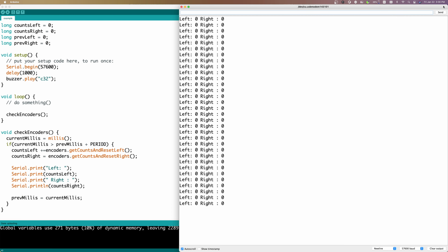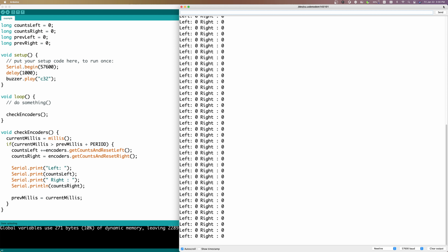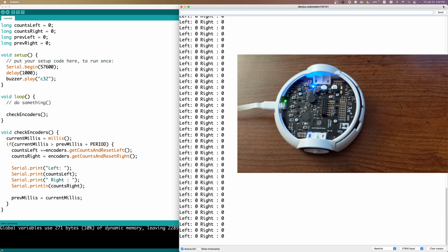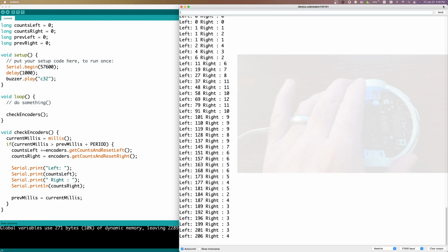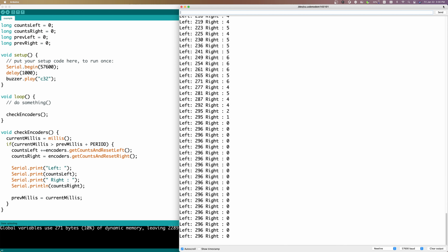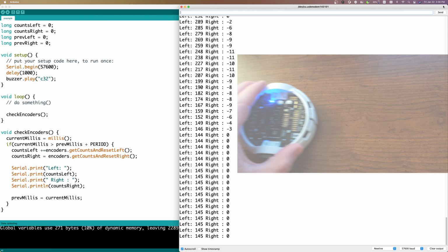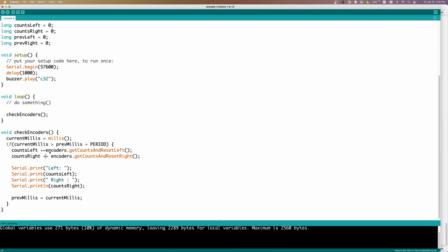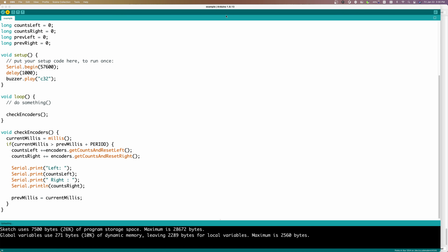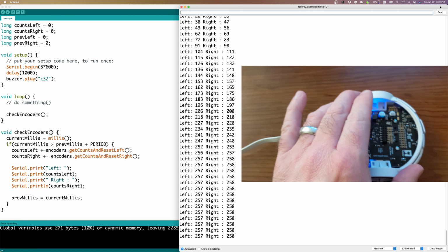And there you go. You can see our left and right coming up as zeros. Now, of course, I haven't applied any motors. I took that code out. So I'm going to physically move the robot, and you can see that one of them is going up. And notice the other isn't, because after giving that whole speech about adding continually and not replacing, I didn't do it for the right one. So let's reset that and do it again. And there you go. That's much better.